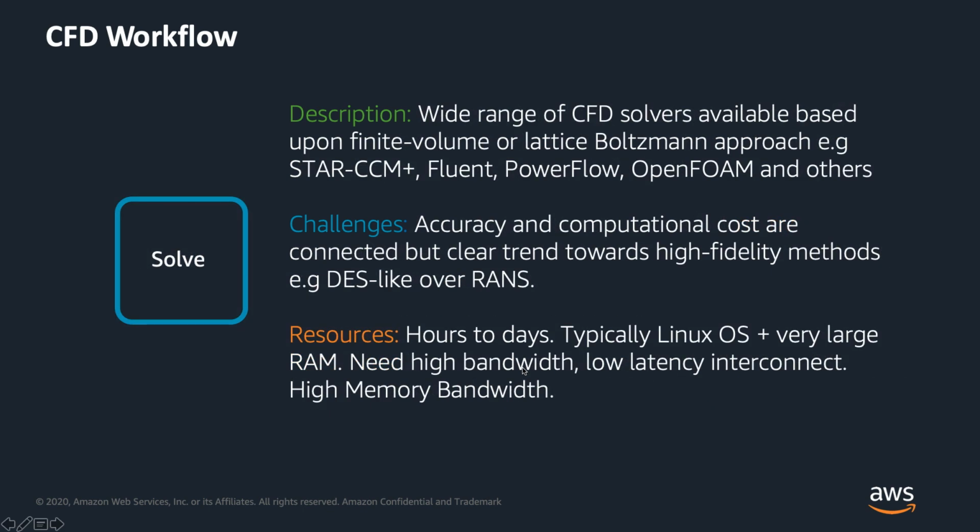Of course, the key one is the solve. Ultimately, you're going to solve some equations over the grids that you've generated. Broadly split among the finite volume codes, StarCCMs, your Fluents, your OpenFOAMs, and then the lattice Boltzmann codes that are quite popular in the automotive space, like PowerFlow. Many others here, of course. The challenge is really accuracy and computational cost, and the fact that they are very clearly linked. So you really can't get one without the other.